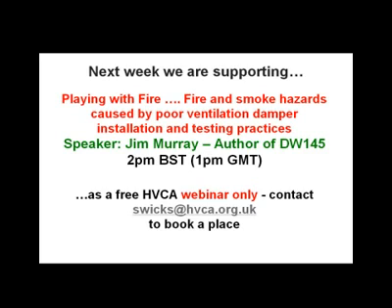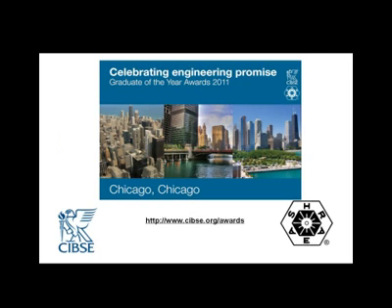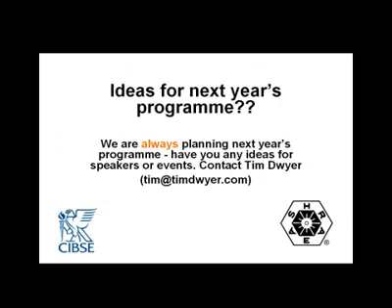Yep, well the answer to that is yes, in a perfect world that would be the case, but unfortunately we don't live in a perfect world. Very often boiler plant is inherited, the goalpost moves, buildings evolve over time. When the original design of that plant was done, in the perfect world it was never going to dry cycle, it had fully modulating burners that had high turndowns, but as things have increased and things change, i.e. higher efficiencies, that boiler plant design is suddenly put under different criteria.